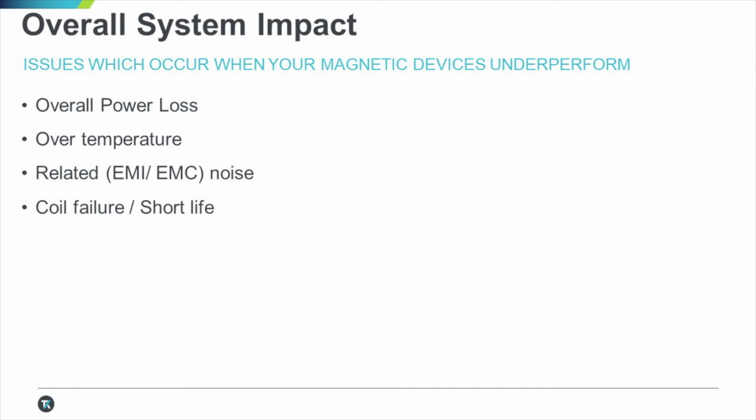Proper measurement and understanding of your in-circuit magnetics plays the following roles in your overall system design considerations. Such measurements include power loss due to the inductors and transformers, which, if not handled correctly, result in heat. Reducing losses helps reduce heat generated, and you also want good heat dissipation mechanisms. These issues cascade to other system considerations, particularly operating over temperature specs.